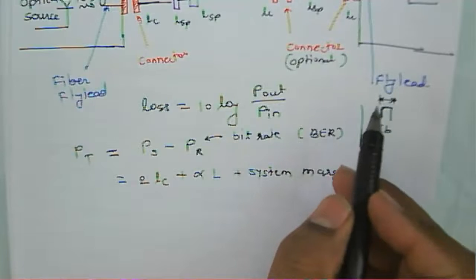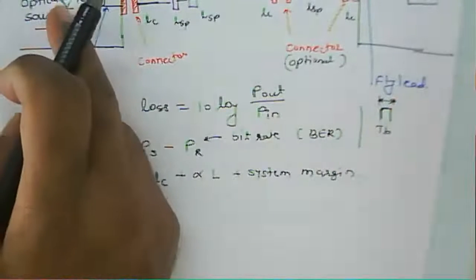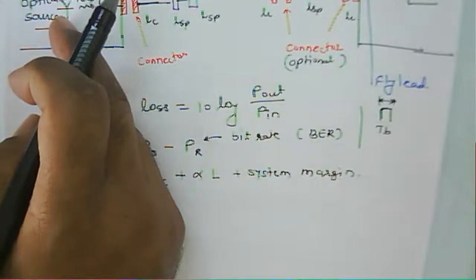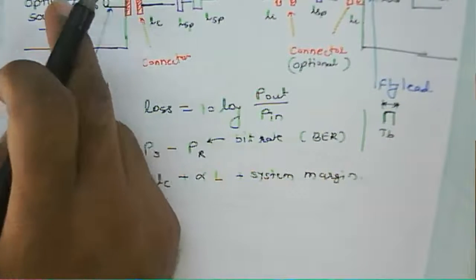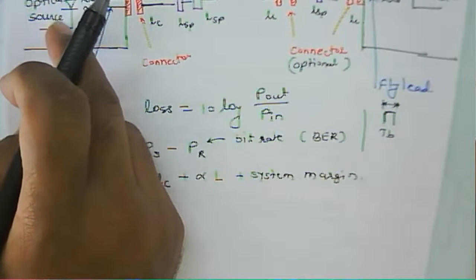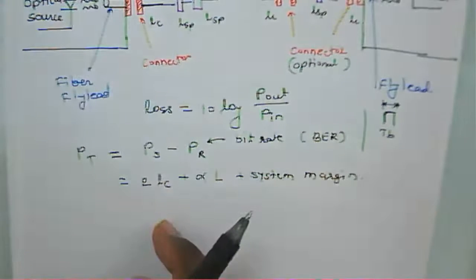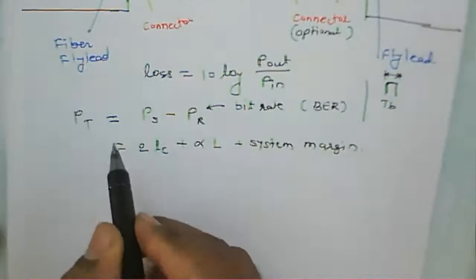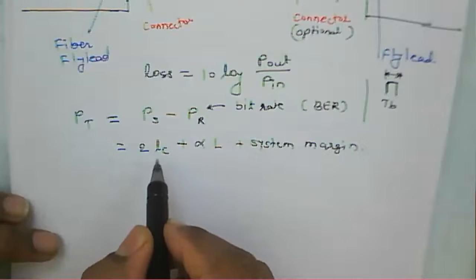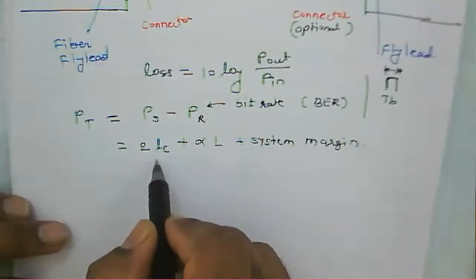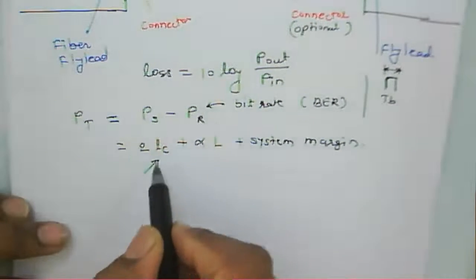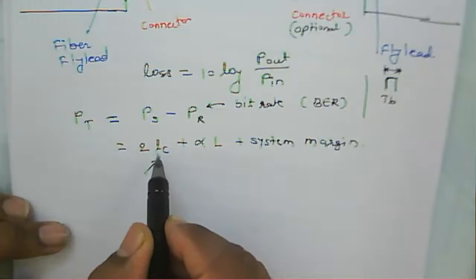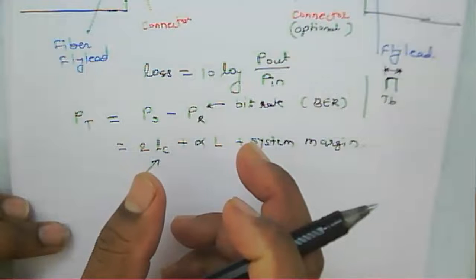And that is the format we are using while transmitting the signal from the transmitter side. So we have a given particular source and we are transmitting some power there. Now for the given link, along with the sensitivity part, we need to know the losses for the given length of the fiber.